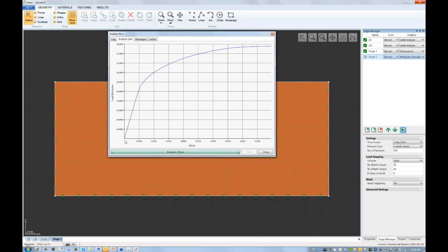So we start down here from no load at all, then we have an initial almost elastic, or in any case linear, part. We come up to the working load, which was 100, and this is the part on the curve where things go from being linear to becoming more and more plastic. You lose stiffness basically. So that's probably where we want to be.